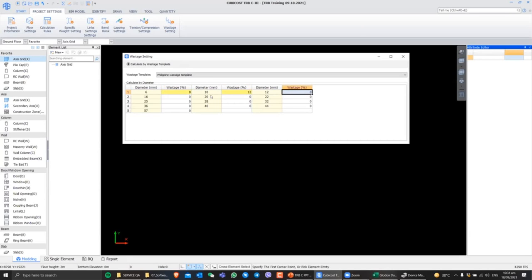If you compare the bidding weight to the construction rebar weight, there is a difference. In the construction process, a contractor estimates the wastage they get on site versus when they bid, and usually they arrive at a certain percentage when comparing these weights. Maybe on most of their projects they get around 15% wastage in terms of estimate.